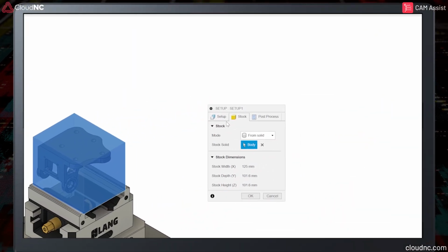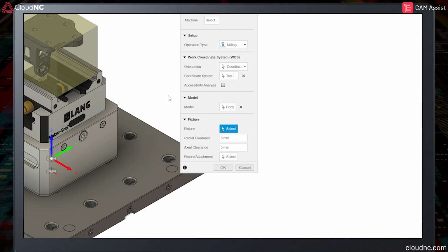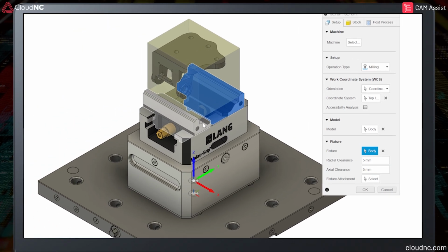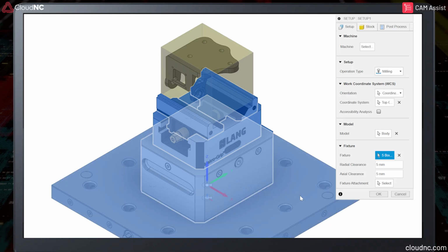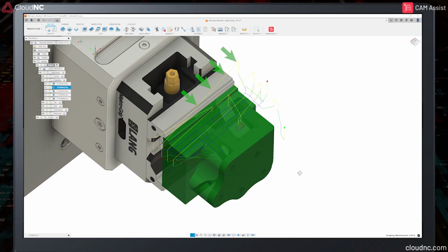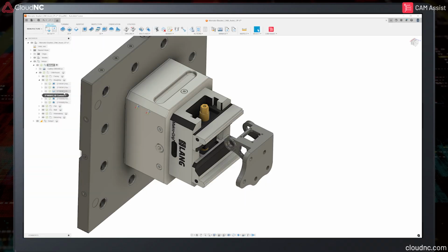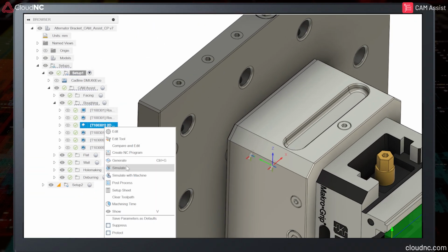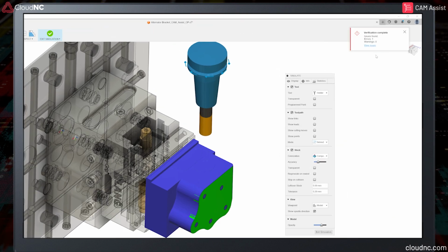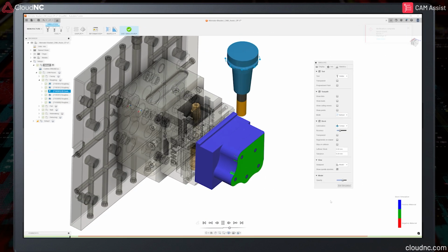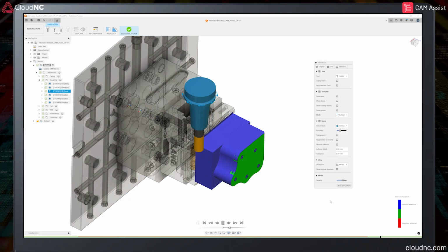It is critical to define the work holding within each setup, as this plays a vital role in CAM-Assist toolpath generation. This is because the defined work holding area helps CAM-Assist understand the maximum depth that the toolpath can go to for each operation, ensuring that the toolpath does not collide with the fixture area. It is vital that the user reviews the toolpath generated by CAM-Assist before post-processing any code to the machine. In the unlikely event of a collision, the user will be alerted to the issue when reviewing the program if the work holding is defined in the setup correctly.